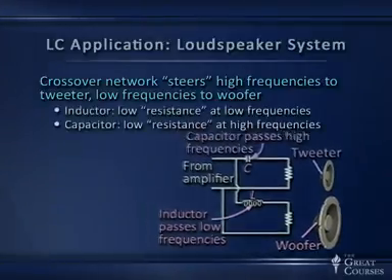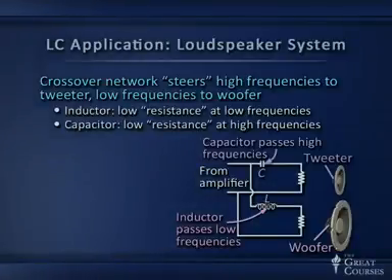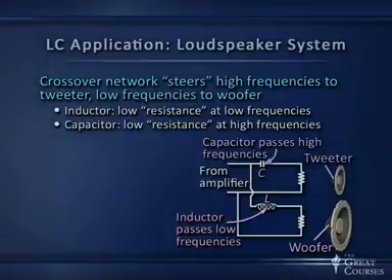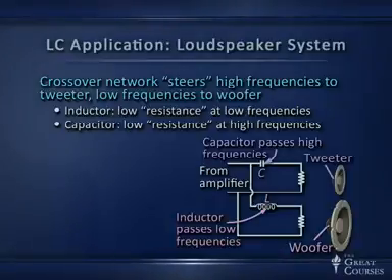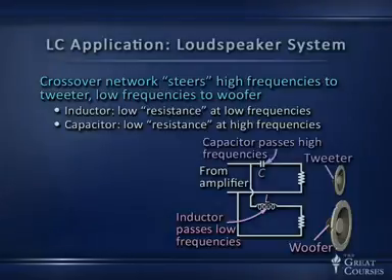And how do we do that? We use inductors. Inductors pass low frequencies without much so-called resistance. They don't have much reactance. They let low frequencies through. Capacitors let high frequencies through. And so this simple circuit shown on the right drives these two different loudspeakers, the small tweeter that responds well to high frequencies and the big woofer that responds well to low frequencies.